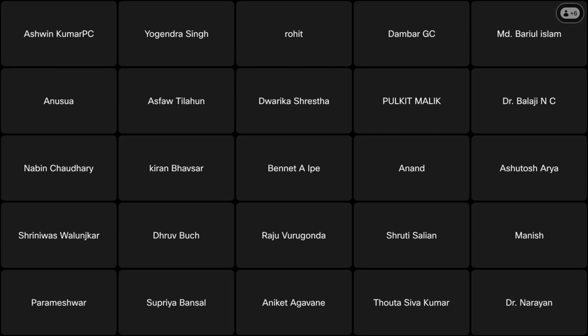Sir, but we can design BRB in such a way that it will follow the double stage yielding. No, that is what we want. Double stage yielding in the sense that in tension and compression, it has to yield. It has to function as per the basic property. Like a CBF has to do, BRB will also do the same thing. It will yield in tension. It will go into multiple modes of buckling in compression.